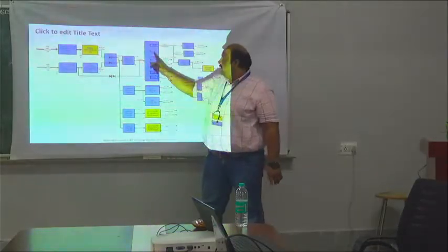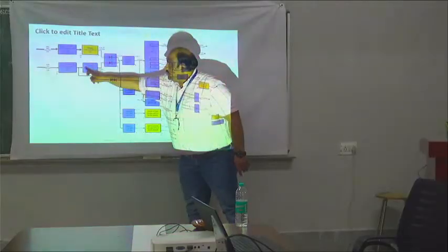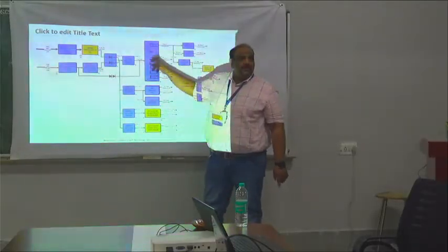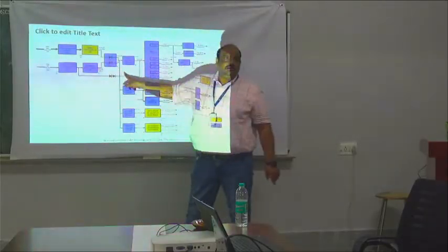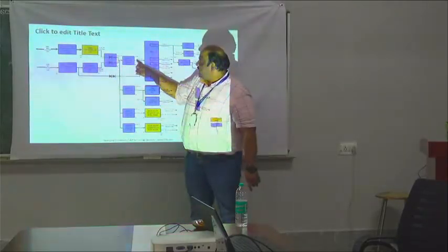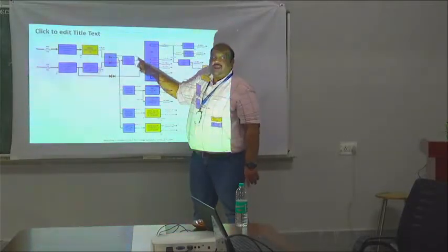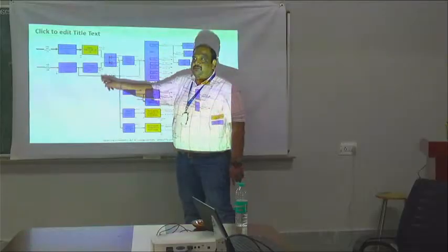Initially, to wake up this unit, it has to be driven by this one. For the wake up itself, we have one more signal which is a double diode, which will give a certain voltage here. Once the voltage comes from here, this voltage will be higher than this, this diode will be reverse biased, and this path will be off.